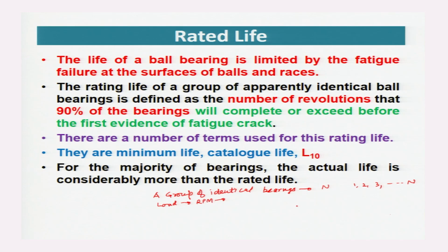Then all will be observed for the first evidence of fatigue crack. Then the rating life of this group of identical bearings is defined as the number of revolutions or cycles that 90% of the bearings will complete or exceed before the first evidence of fatigue crack.